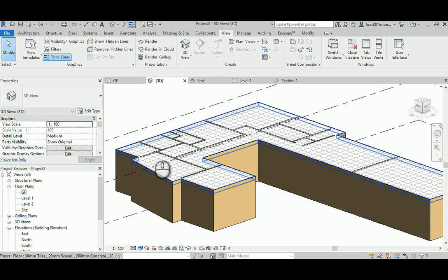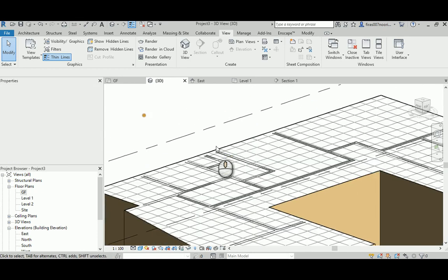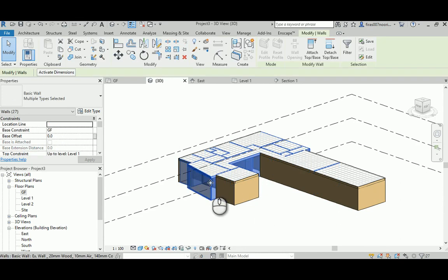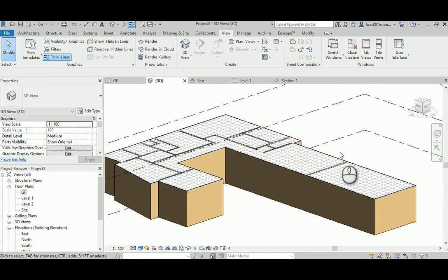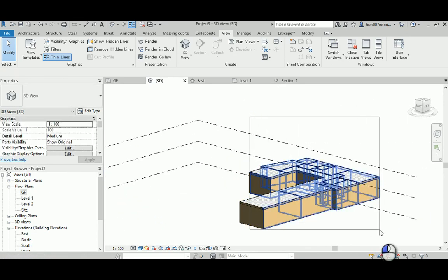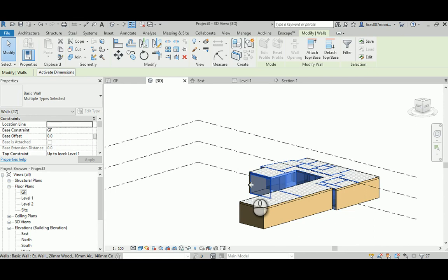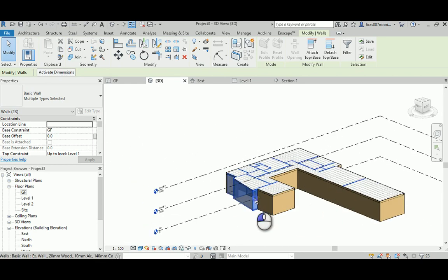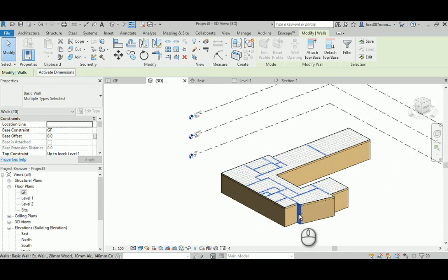Now the inner walls, the partitions, are just making an annoying thing. So I'm going to select them, and I need to select those, and I'm going to remove from my selection the outer walls, because the partitions are not really accurately attaching the slab.